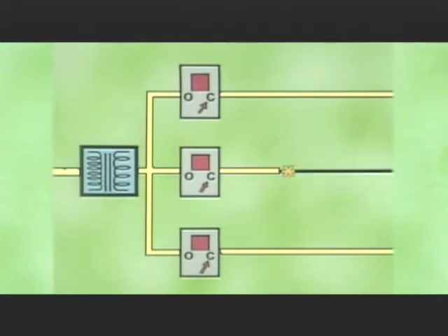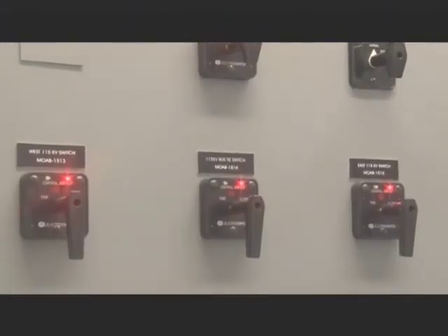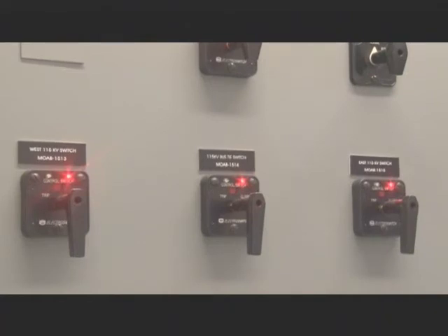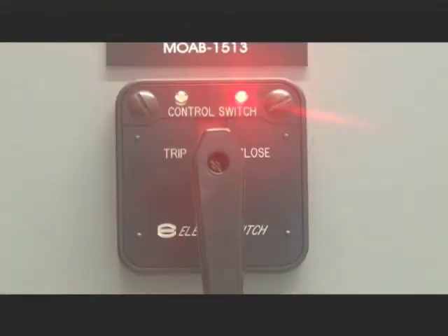However, if the fault does not clear, the current carried by the feeder will continue to flow to ground. This will cause the circuit breaker to open again for a period of time and then close. In some systems, this pattern of opening and closing will continue until the fault is cleared. In most systems, however, the circuit breaker is designed to open and close a set number of times and then lock out. That is, remain open until it is reset manually. Circuit breakers provide excellent protection against damage due to faults on feeders. Circuit breakers can also protect laterals that are tapped off of feeders.